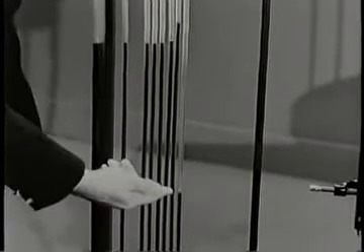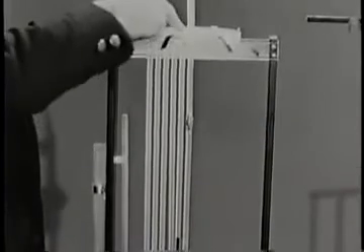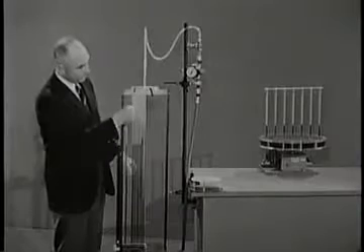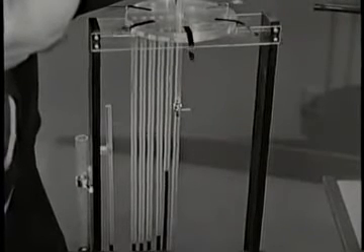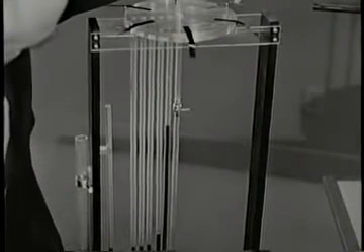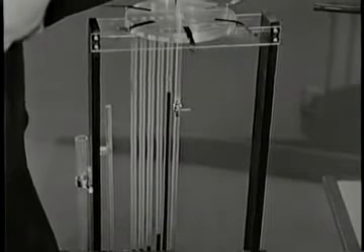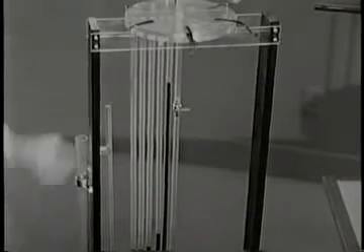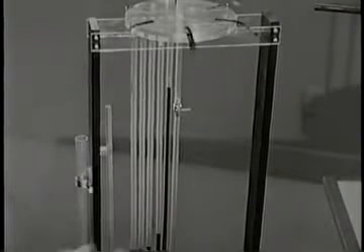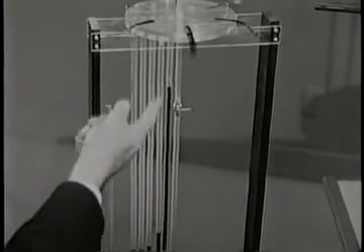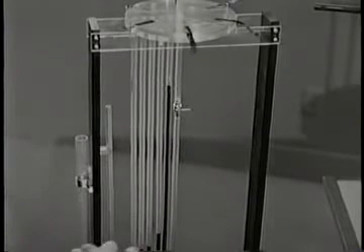At the axis, the pressure is greater than atmospheric by an amount equal to the dynamic pressure of the air jet. Over most of the plate, though, it is less than atmospheric, and rises to atmospheric pressure at the outer edge.